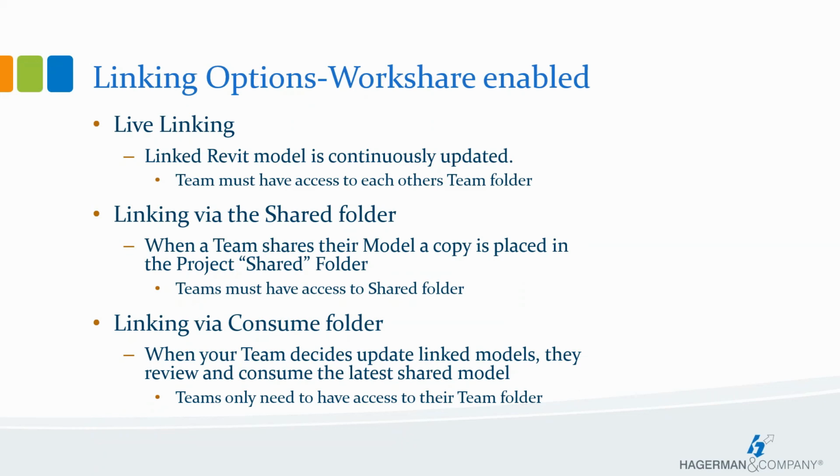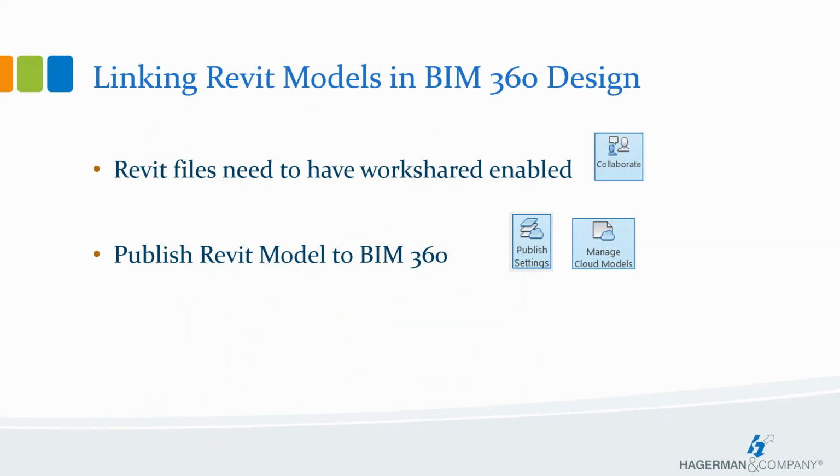Through this consume process, it actually takes and moves the file to their working team's folder and puts it into a consumed folder so that the team can continually work within their own team environment. So if you're the architect, you'll have an architectural team folder and all of your work can be done there through the consume process instead of having to have access to another team's folder or to the shared folder. For linking, you can always still put things in the shared folder, but we're talking about linking for this.